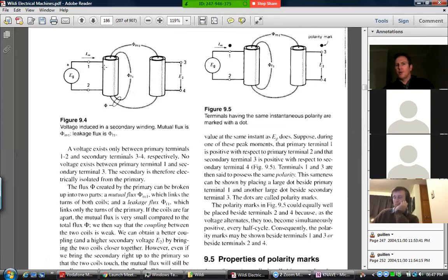So that's a coil there, the primary side. That's your secondary coil. Any side that is receiving power from some source is going to be your primary side. And this one would be where we're putting a resistor or something, a motor, whatever it might be, between those two terminals. So that's where we're delivering electrical power to. That'll automatically be called the secondary side, regardless of whether we're putting voltage step up or step down. Primary would be the power input side from a voltage source, typically, and the secondary would be the electrical output side.